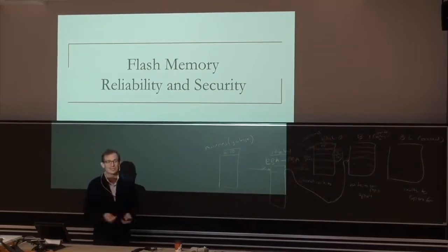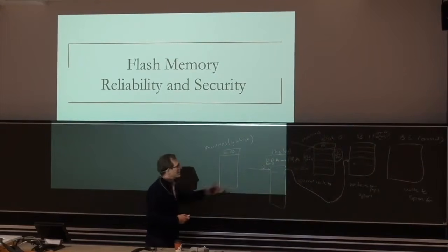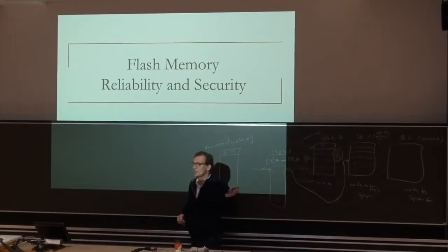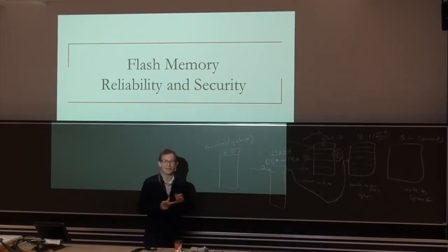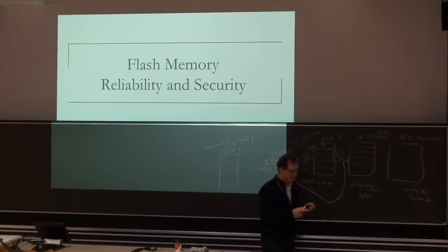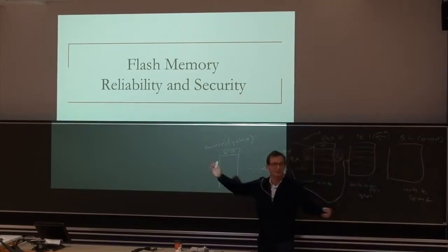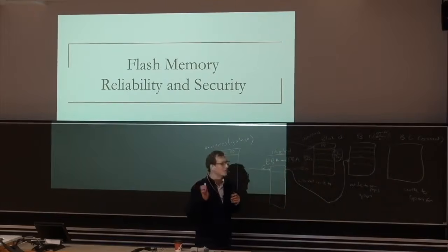So controllers are doing this in the background all the time to ensure that they have enough space over here. And this is happening because the read granularity is at the page level, and the erase and program granularity is at the block level. And the block level is huge. And that is there because of technology constraints.